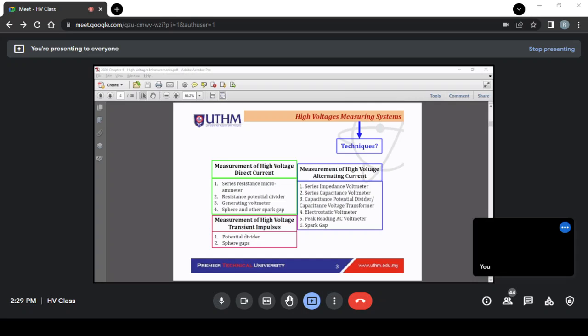And the 10 volt, we measure by using a normal oscilloscope, a normal probe, or a normal multimeter, and it will indicate 10 volt. If we see the probe is showing 10 volt, then we know the high voltage source is actually 10 kilovolt. As simple as that. This one can be very high, as high as a normal human height of 1.5 meter, or maybe more.